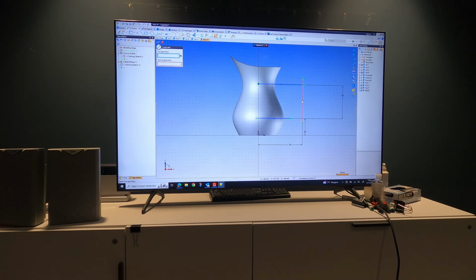So what we're trying to do is not move this arc, we're trying to move the center of the circle. Okay. So then we've got to come back the radius to 25, so that center of the circle should be 45. From this line, from the center line, because that's all we know, we can count out to here, it's 70. The only way to count back is to use the radius, so we subtract the radius of the circle, 25. Oh, I see. 70 minus 25 is 45, which is the remainder here. So 45 out is the center of the circle. Yeah, because we can't grab the arc, right? Okay.